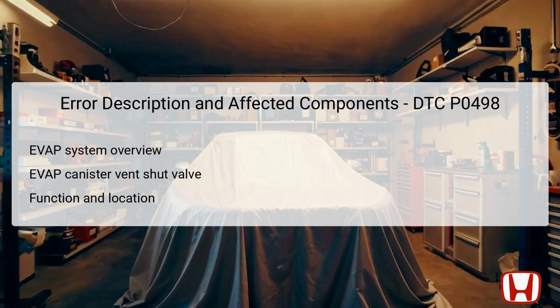Its malfunction can lead to incorrect pressure readings in the EVAP system, affecting overall vehicle performance. Additionally, the valve is crucial for ensuring that vapor recovery occurs effectively during refueling and operation. Identifying its exact position and functional role helps in promptly addressing the DTC P0498 concern.